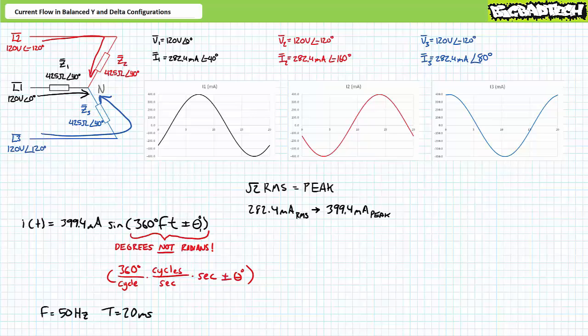We can now perform instantaneous analysis of these 3 time-variant current expressions by substituting a known frequency and desired time values. For the sake of simplicity, let's assume these waveforms all have a frequency of 50 Hz. Yes, I am well aware 120 volt line to neutral, 208 volt line to line light industrial 3-phase AC, commonly available in the US, has a frequency of 60 Hz.